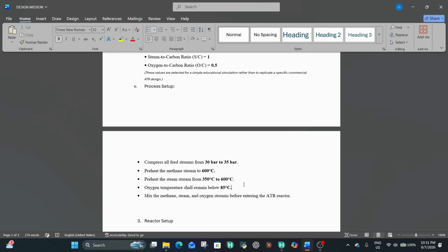We consider safety control factors, and chances are that you might energize the oxygen too much through excessive heating, and that might lead to a catastrophic event such as fire outbreaks or explosions. So usually oxygen is used at room temperature. You could slightly heat it up to improve the process.